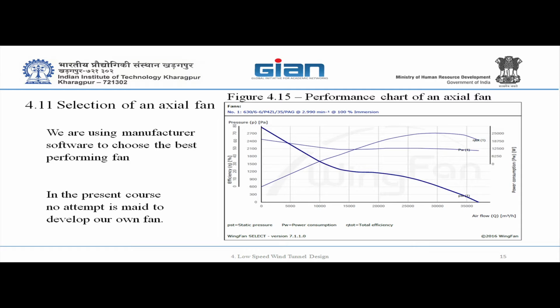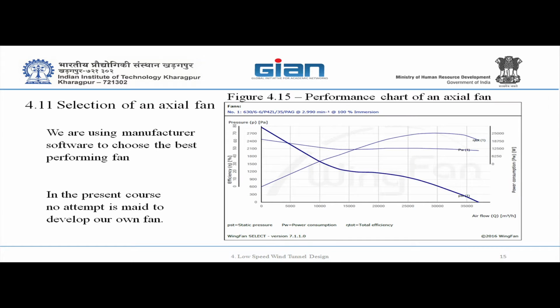Before we break, anything you want me to talk about? Sir, in one of your wind tunnels you had a wide angle diffuser just before the fan. You said that because it will be a noisy flow there, you wouldn't be caring if you had diffusion and you can recover some area. But then, as you just said, the fan has to create a suction in front of it. Wouldn't that cause extra resistance, because you have the slowing down of the flow and some extra pressure building up in front of the fan?